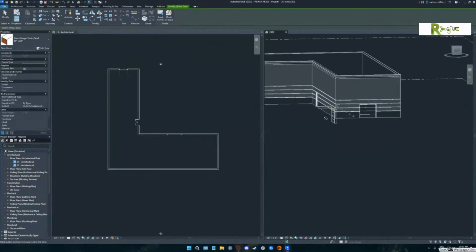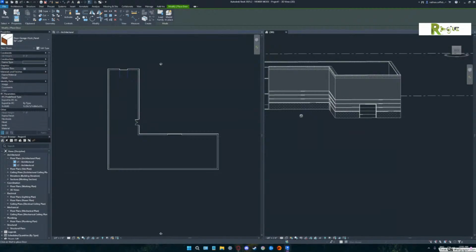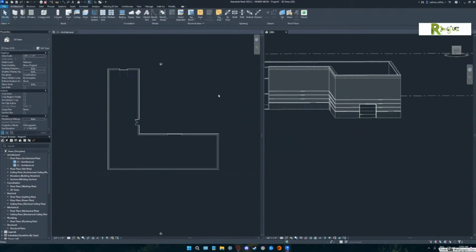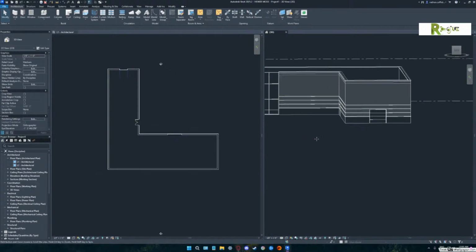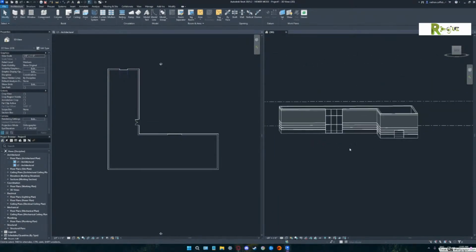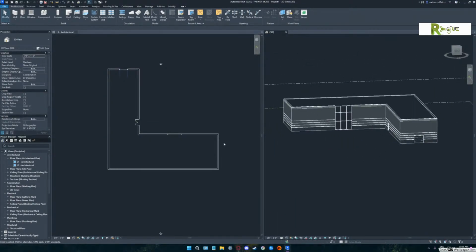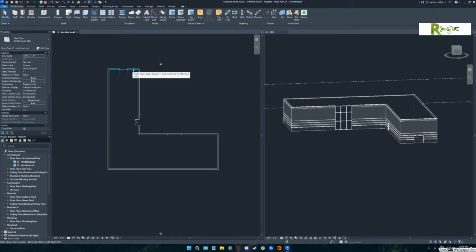So we talked about ways to select objects. Hit escape 2 times. We talked about ways to select objects. Remember, there was that click and drag, and you could do the crossing window or the window. There was the ability to pick one wall, and then to hold your control button and pick another wall. So can you pick the top 2 walls or the top 3 walls right there? How would you pick those 3 walls? You could pick like that.